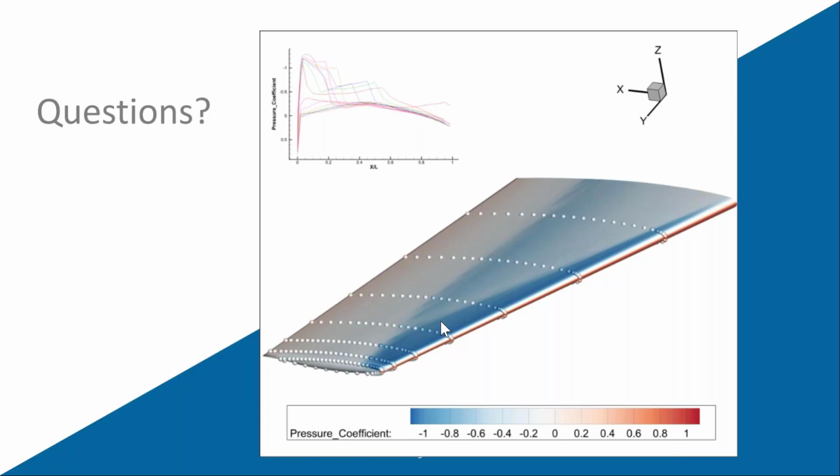Let's see. Can you plot it on the line arbitrary axis direction as the independent variable instead of one of the principal axes? Yeah, and the horizontal axis in the XY plot will be distance along the polyline rather than Y. Yeah, so that's a good question. When we do our extractions, we don't include a distance variable, but you could calculate a distance variable fairly easily with a Python script and then use any other variable on the X or Y axes.